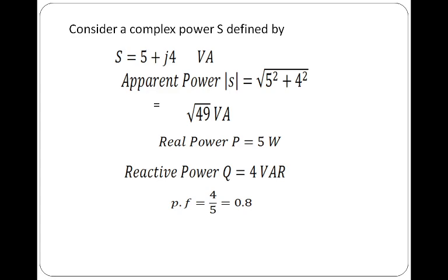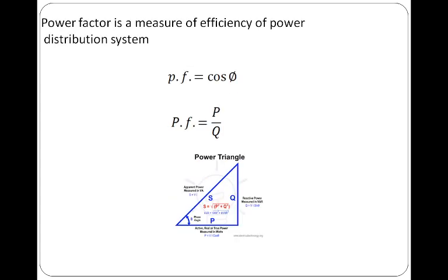We should know that in power transmission and distribution, significant effort is made to control reactive power. This is typically done automatically by switching inductors or capacitor banks in and out, by adjusting generator excitation, and by other means. This shall be discussed later when we deal with how to correct power factors. And it is worthy of note that electricity distributing companies most times provide meters which measure reactive power.